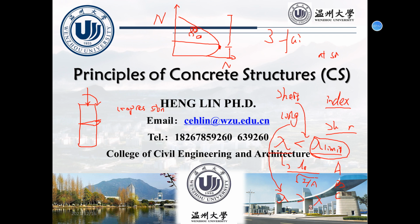The difference between short and long columns is the second order effect. For short columns, we do not need to consider the second order effect, but for long columns we have to consider it. This means the expressions we use are different.